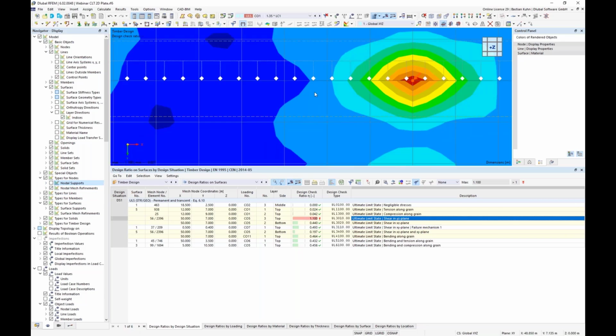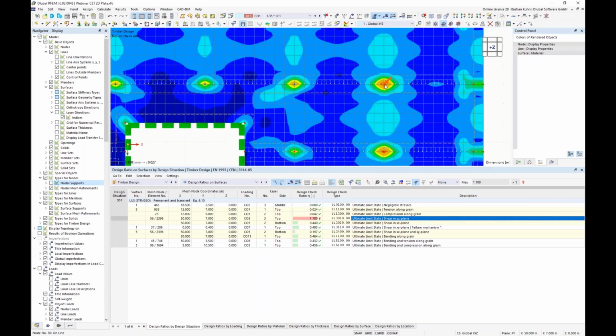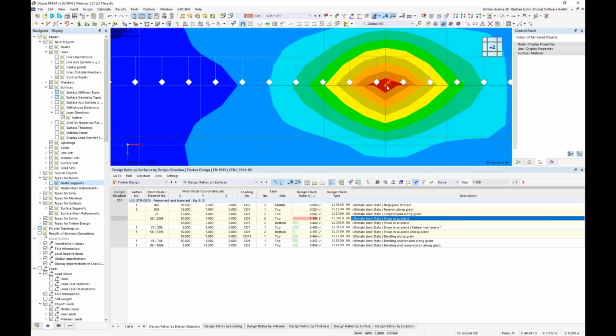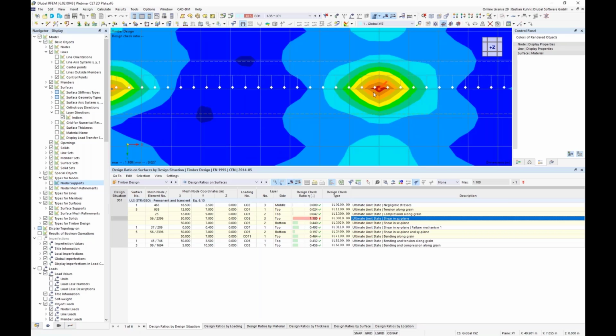And if you realize that in reality there's not a needle standing underneath this point, but a column with a diameter of, let's say, 40 centimeters or something else, it's obvious that you should not take the force in this spot, but you should take the force somewhere outside. And I will actually show you how to do that.